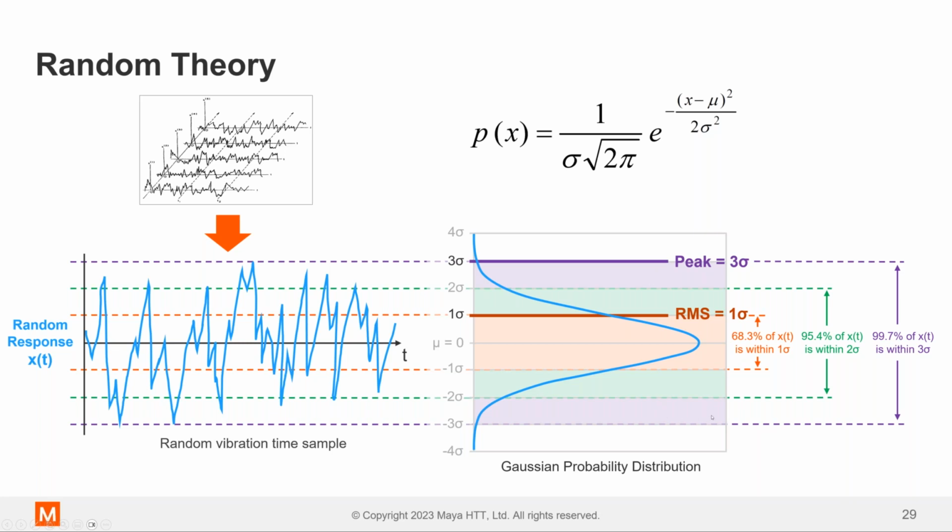And this is just the idea of taking a probability and determining, okay, what am I enveloping enough? Am I designing to the right level? Obviously, you might not be able to design to 1 sigma because that means almost 30% of the time you might have loads, accelerations that exceed that. Well, you've got to design for those.